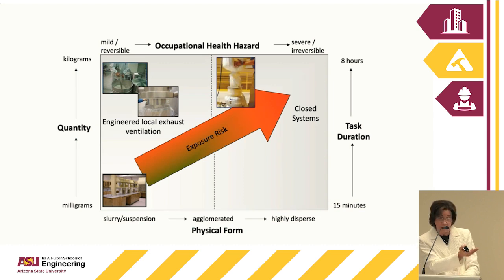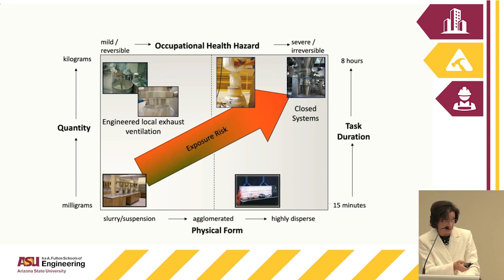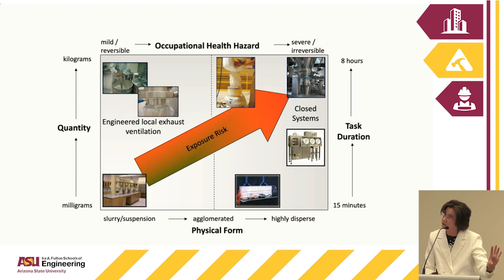And then you have here a bag unit, so that the drug active is coming in through a bag down into the system. And then you go all the way up to a highly contained process, where you have split butterfly valves and a lot of really robust engineering controls. And then even down at the bottom, these are vented enclosures, and then a glove box containment unit. But this kind of really helped inform our design engineers. These conceptually helped them understand where we wanted to head when we had a new chemical process, a new chemical entity. But that has to be designed for your process.